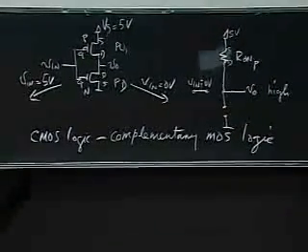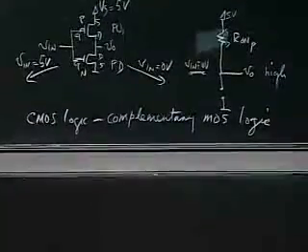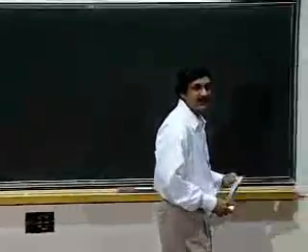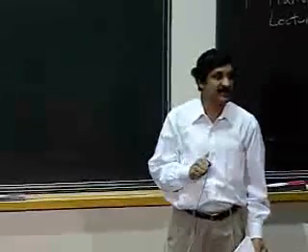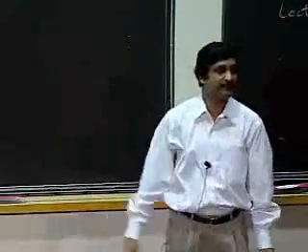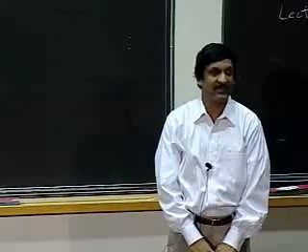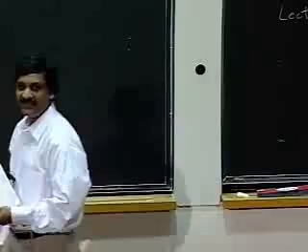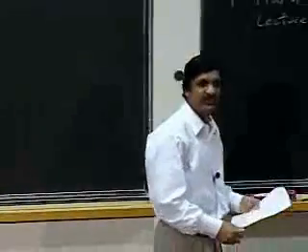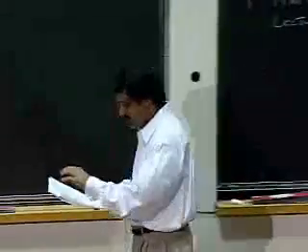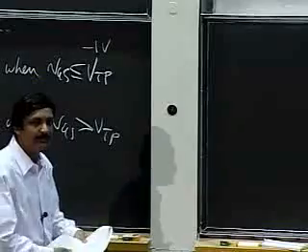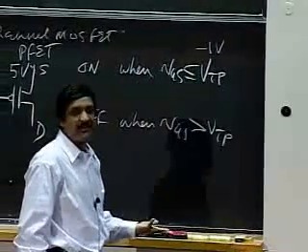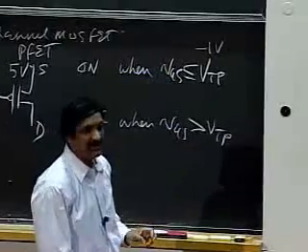So what you've seen here has been the workhorse of the digital industry for the past 2 decades. 20 years, CMOS logic. Okay, and even the most advanced chip from Intel has an inverter that looks exactly like that. If you count all the inverters in the universe today, I would say a significant fraction of those look exactly like that. No difference. It's just so simple. So the key with something like that is there is no path from the power supply to ground, and so by that model, I do not consume any standby power. Okay, my standby power in that idealized model is 0.